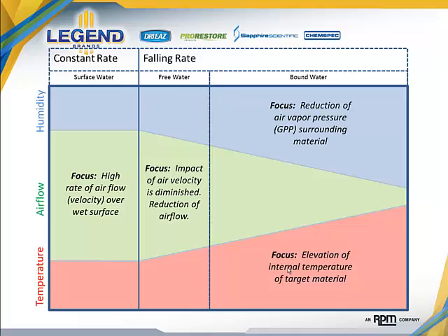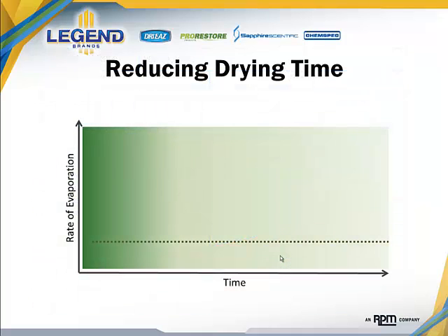Again, we've discussed both of these concepts in earlier modules, and they will be discussed again in more advanced application as we move forward with our modules throughout this year. When we leverage these properly, the overall impact on our drying times and drying rates is extremely dramatic. Without the application of air movement on the front side of the process, drying rates are exceptionally slow. They're a natural drying rate. Building materials without the implementation of airflow initially are going to dry at basically the same rate as if a restoration contractor had not been engaged at all.